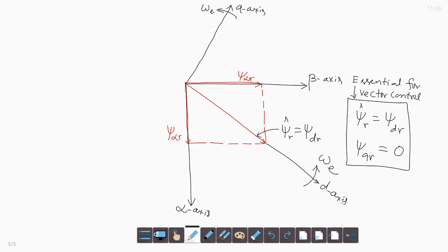And we have the d axis stator current I d s, which is the same as the command value, and also I q s, the torque component of the stator current, which is the same as the torque component of the command value.